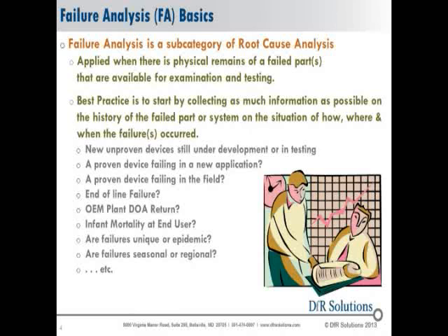Or is it a proven device that suddenly started failing in the field that it's been working reliably in for years, which might indicate that you've got some kind of quality spill going on in either your assembly or your supply chain processes? Is it an inline failure? Are they coming off your line and all of a sudden you're having some kind of assembly or fabrication problem? Are your OEM equipment customers returning them from their plants because they're dead on arrival? And maybe there's something happening in shipping there. Is it infant mortality at the final end user?